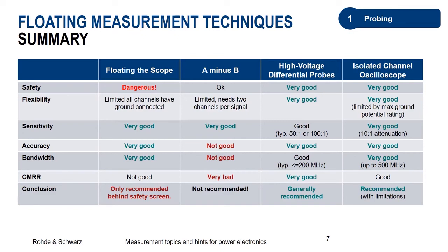Usually you have on such probes 4 millimeter connections and cables and maybe some kind of alligator clips or something. This kind of connectivity will not allow for good measurements above 200 megahertz.